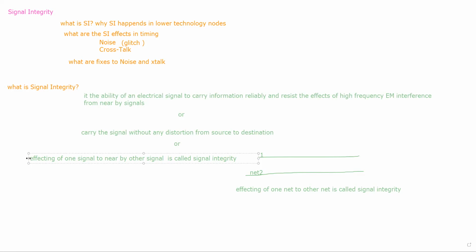So if your gate count increases, what about your connectivity, guys? If your logic is increasing, your gate count will be increasing. If your gate count increases, will the number of pins increase or decrease? Increase. If the number of pins increases, it demands more routing connections, right? Let's say you have 100 pins, then it demands 100 connections. In the latest technology nodes, we have 1000 pins, so 1000 connections are required, right? Area-wise, we are seeing the same area being used.